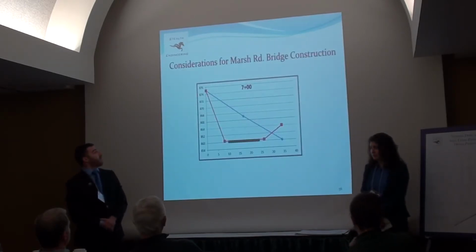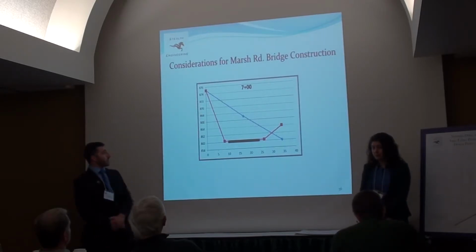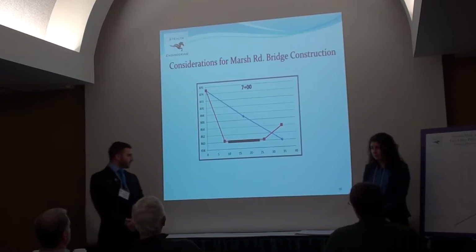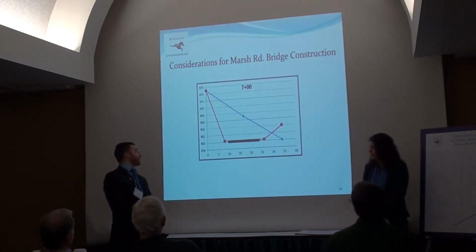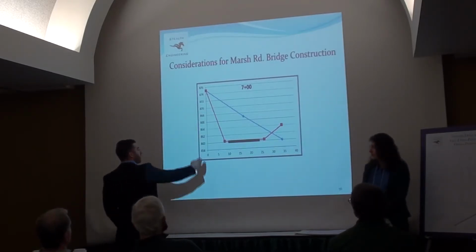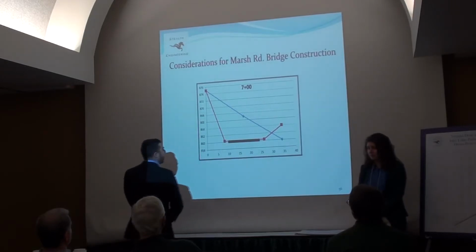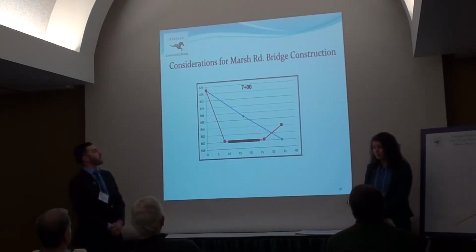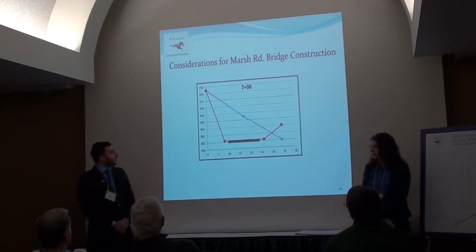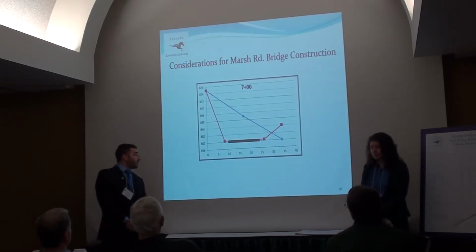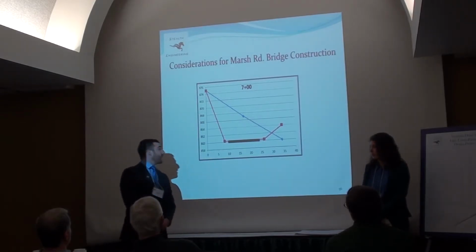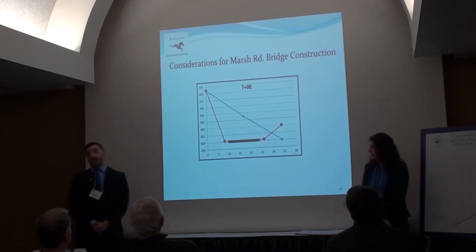Some considerations for the upcoming bridge construction on Marsh Road. This station corresponds to the location that will be underneath the bridge. Currently it's oriented about 8 feet off of the north side of the right-of-way of Consumers Energy. So if any new piers are to be constructed during construction of the bridge, it's important that our current orientation at this station for the bike path is noted.